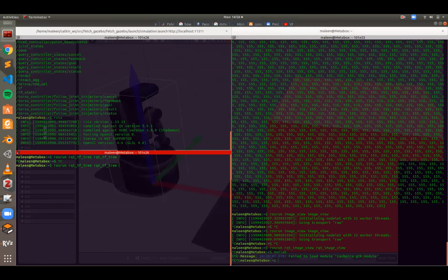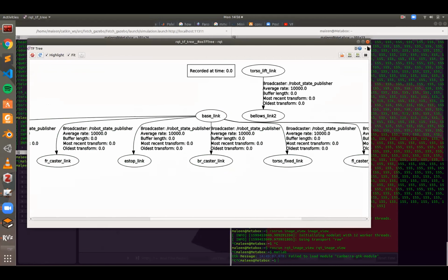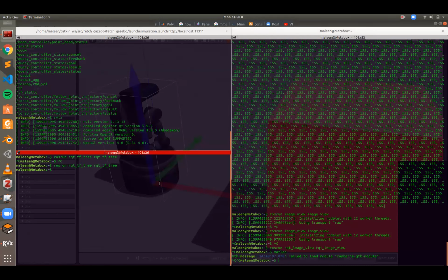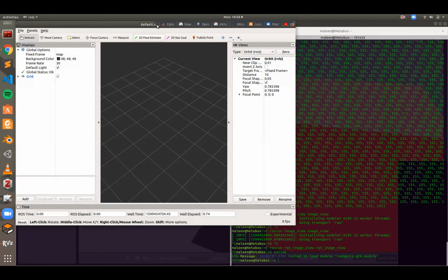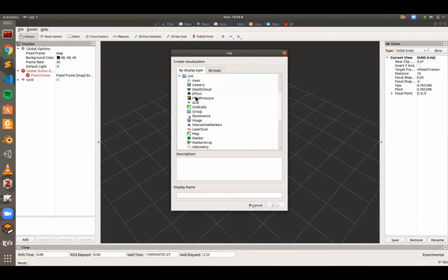So all the different coordinate frames that you have to deal with, you can visualize using this tf tree command, right? So you can see, for example, where the camera is associated with the rest of the robot, and you can even visualize it in RViz, right? So if you launch RViz, you can add the transformations, right? So in ROS, you can call them TF for short.